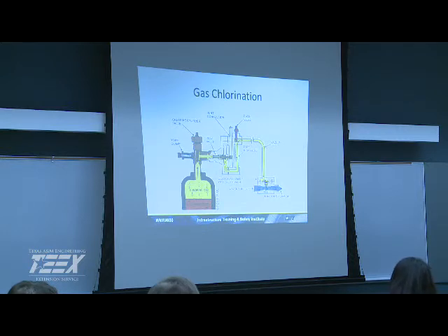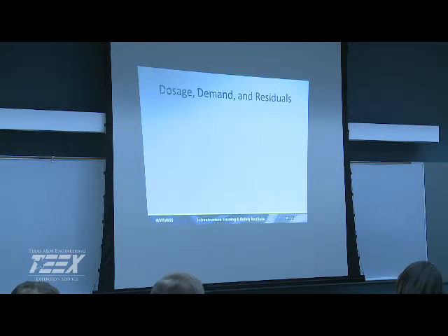That was our wastewater treatment facility. Our large one was pushing about 100 million a day, but wastewater has high demand on it. So they were using a lot of it. And then not only do you have to chlorinate, but at wastewater facilities, you have to dechlorinate before you send it out to the receiving streams.